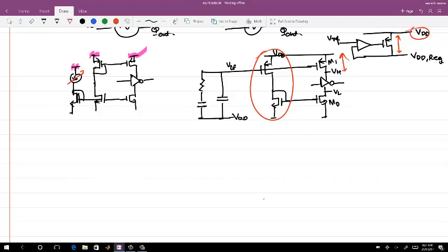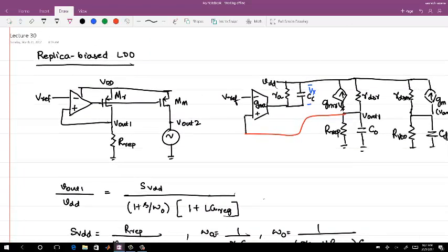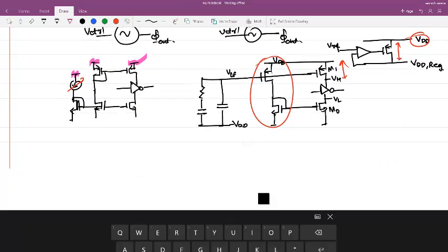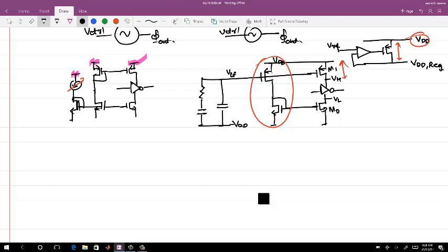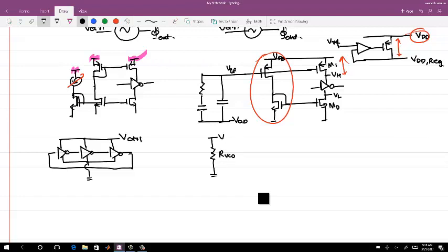Okay, so the other part which we were discussing yesterday was designing our replica with respect to the VCO. That was where we left. So we have an actual VCO, and we modeled this VCO, let me call this V control itself, effectively with a resistance in all our analysis, which actually consumes the same average DC current as the VCO consumes.